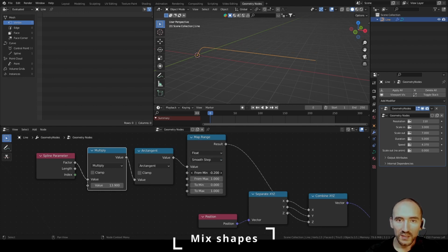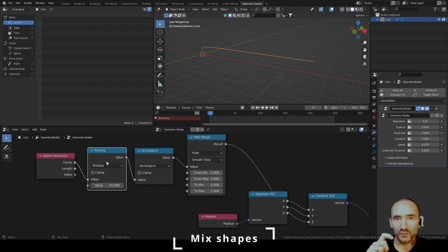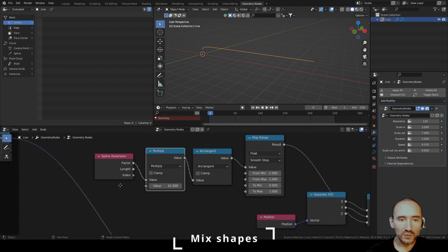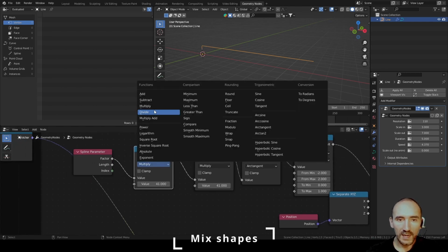And we can see if I increase or decrease the min and max value, we can adjust this number together. I can set this -2 and this 2, for example. So you can see that we never have a negative number. So to have a negative number, we have to subtract a value from the factor to have a better range of values with positive and negative numbers. So I can use an add value.